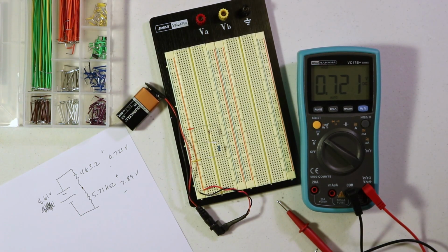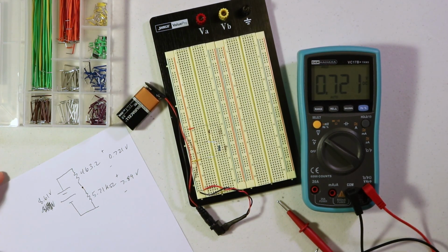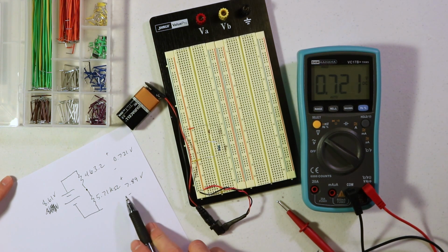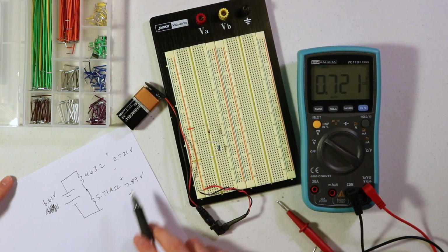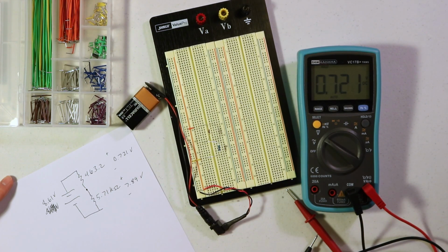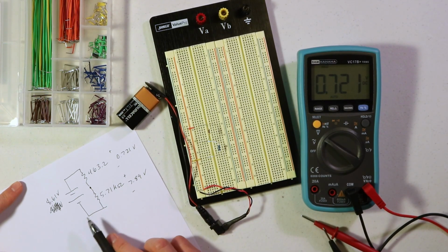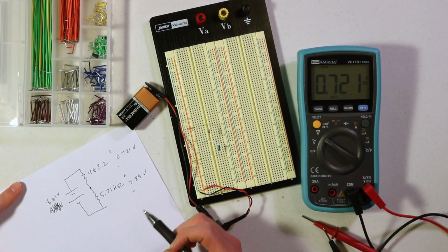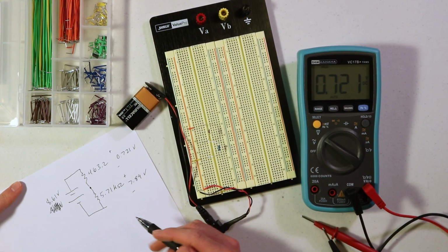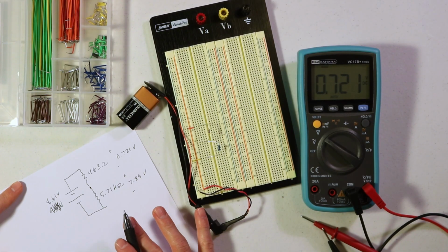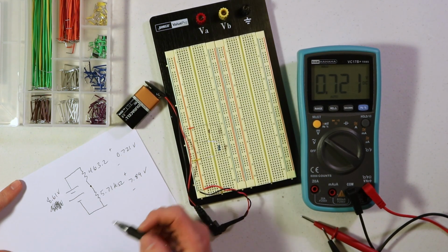Now the thing you want to notice here is the ratio between these two. So we've got more of the voltage across the higher resistance one and less across the other. And when you study Ohm's law later in the semester, you'll understand why. But just for now, this kind of a setup is called a voltage divider. And the reason it's called that is just because it divides the voltage in two. And this will be important when we look at our next thing, which is the potentiometer.